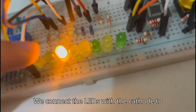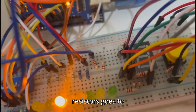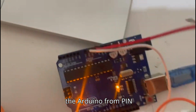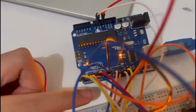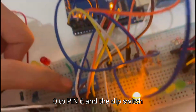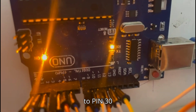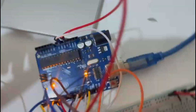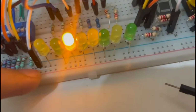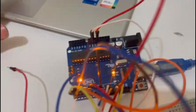We connect the LEDs with the cathode to negative, and the resistors go to the Arduino from port 0 to 6, and the DIP switch goes from port 8 to port 13, and on the cathode side, on the negative, we connect ground.